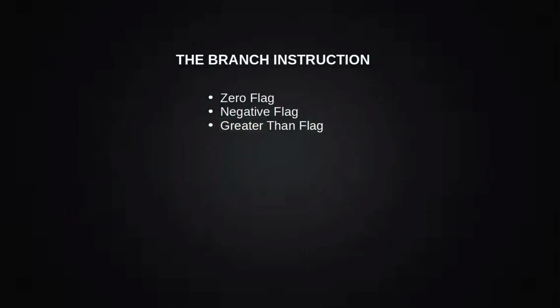Now, I mentioned that you can use flags to control branch instructions, but now the question is what kind of flags should you include? I mentioned in the ALU video that there are all kinds of flags that you can have. Well, what are the most common ones that computers tend to have, and what are they for? Well, on top of the standard ones like equal to, less than, or greater than, you can also have flags like the carry flag, which can be used to indicate if an integer overflow occurs.